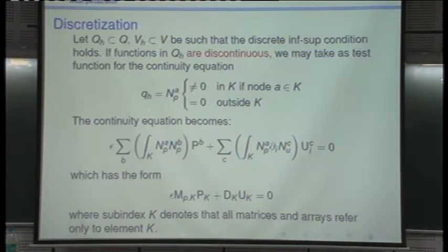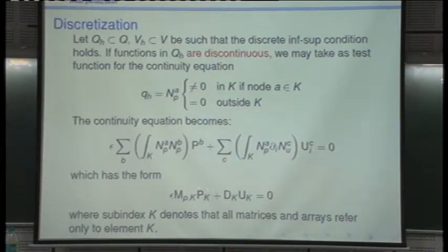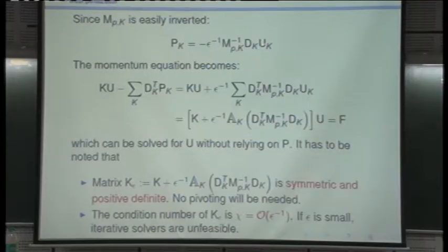You see? And the other matrix is bigger, of course, since the velocity interpolation is continuous. This is a matrix with 3 pressure test functions, but as many degrees of freedom for the velocity as needed. But the important point is that this matrix is 3 times 3. And we all dare to invert matrices of dimension 3 times 3. So we can explicitly eliminate, or compute if you want, the values of the pressure inside element K from this expression. We are able to do that.